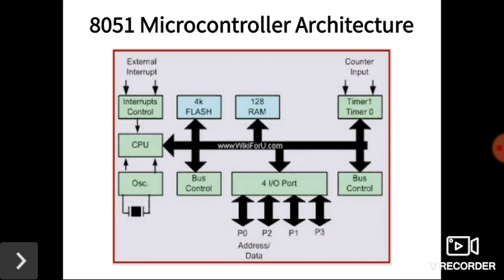An interrupt gives us a mechanism to put on hold the ongoing operation, execute a subroutine, and then resume the previous operation. The 8051 microcontroller can be configured in such a way that it temporarily pauses the main program at the occurrence of interrupts. When the subroutine is completed, the execution of the main program resumes.